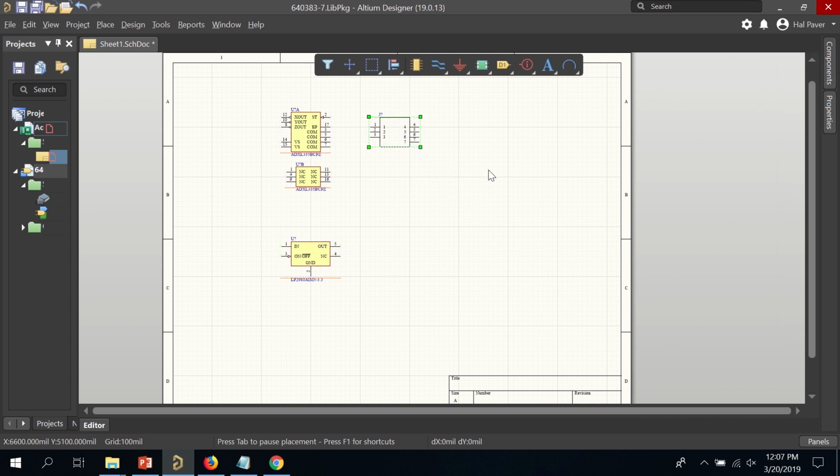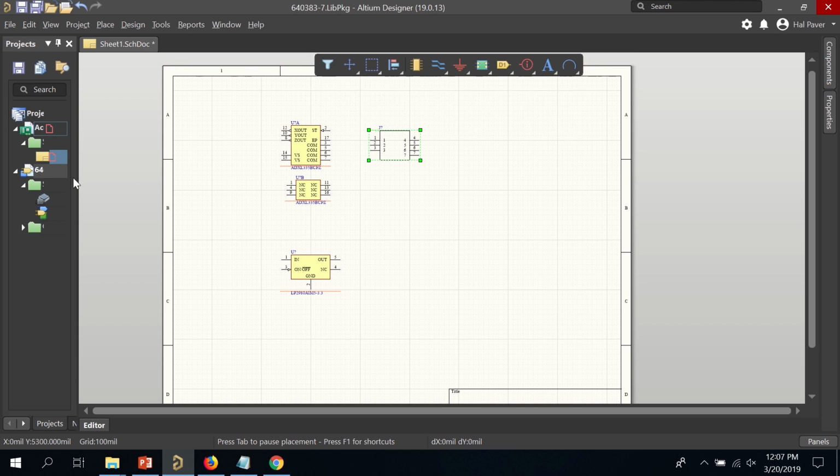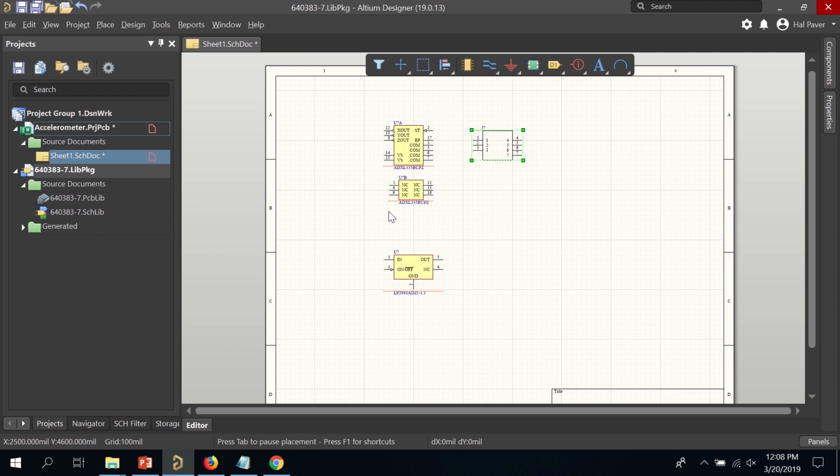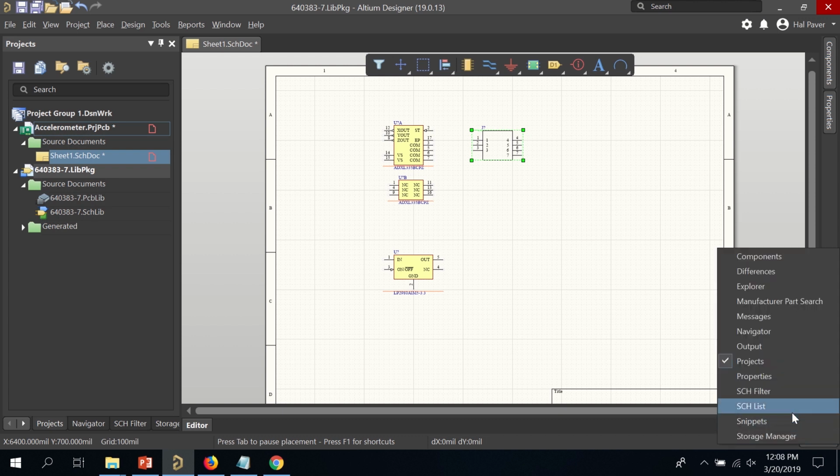And so that's the majority of the components that we need, but we'll still need some passive capacitors. At this point, you could choose a very specific capacitor made by a particular manufacturer at a specific value, or what I'm going to do is put a generic capacitor down that has a specific size but no specific value or manufacturer, and I can specify that later on my bill of materials if I'm getting it outsourced, or if I'm assembling it myself, I can just use whatever components I choose to buy.